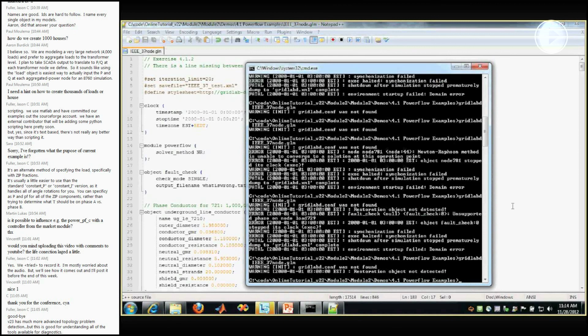The alternative to that, if you're doing a very simply connected system, but you have a lot of houses, if you don't want it to be deterministic, you can basically do how we did on the 4-node system, where you can do like the house, the colon, and then 10,000 or whatever. But for most realistic simulations, that's not a very good approach, just because since it is randomized, you'll get a different answer every time you run GridLAB-D, basically.